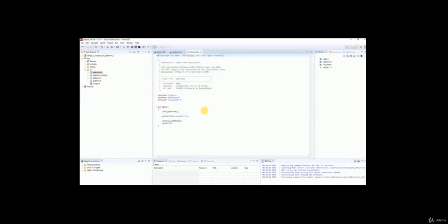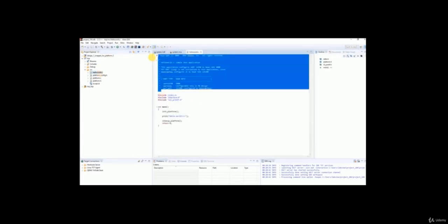You'll find that code has been provided for us. We'll delete the comments. Three libraries have been included right now. The first one is stdio, then we have platform.h, and then xil_printf.h. These three headers have been added with the Hello World template. The init_platform and cleanup_platform calls are the preliminary settings required to work with a UART.